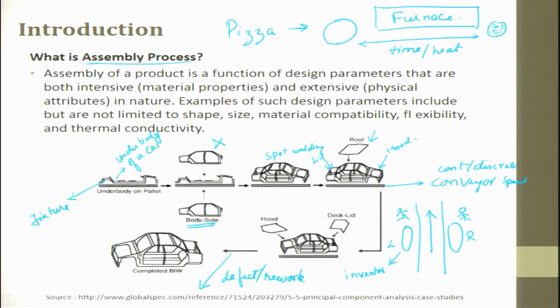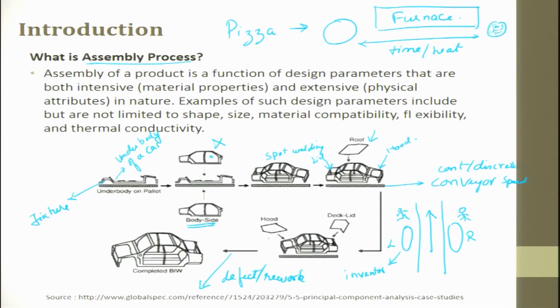This is also possible: if it is only one defect and it is peculiar, which is not going to get continuously repeated, then they say okay, let it go and we will pull it out and rework only that car, but the rest of the cars go on fresh. Suppose there is a major defect in the metal working operation, a hole or a dent, then the entire car is pulled out and reworked, and the car goes through every station, spends that time, and no work will happen on the car.